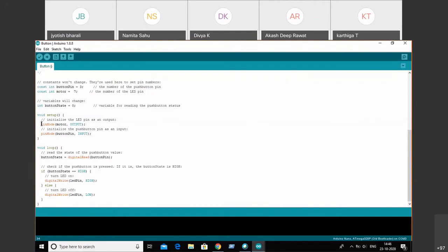In order to set up a pin, you need to declare the data direction register, data port register, and then the pin register, so that you tell the compiler whether this pin is an input or output pin and where it belongs, the address. Here we can just write pinMode. See, this is the encapsulation and the abstraction that I was talking about. A very long piece of code has been shortened into a very small form factor.